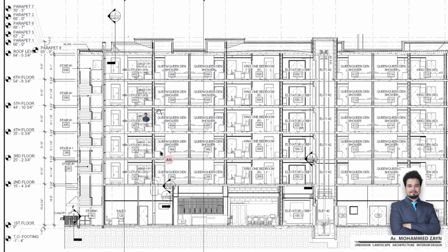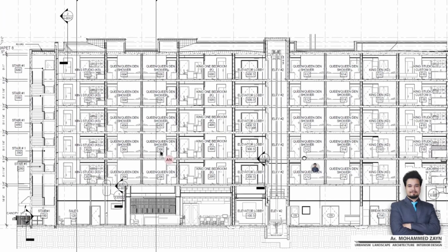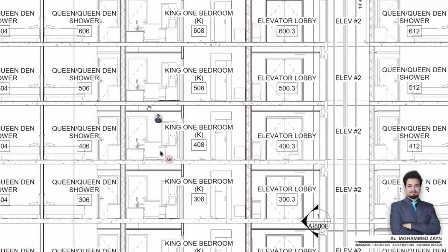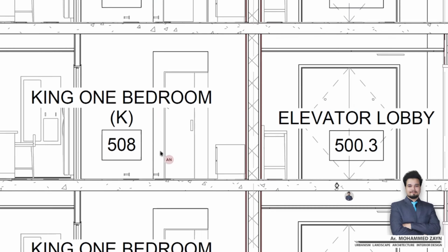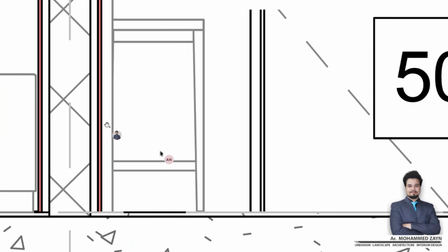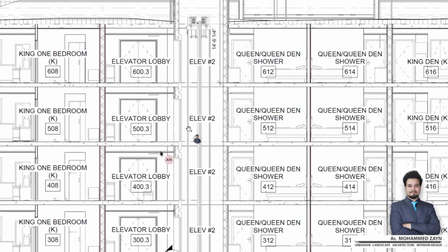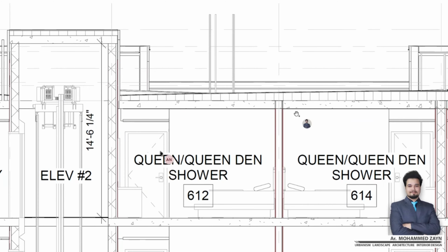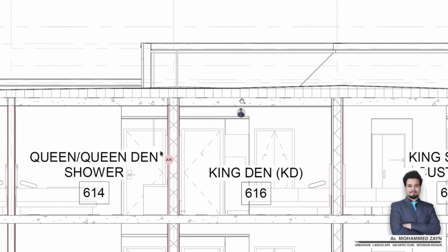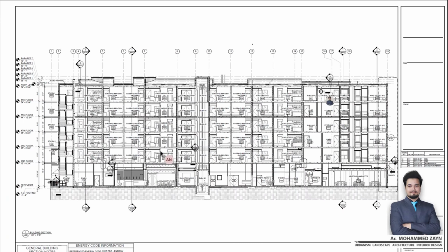These are the sections that we have created. So you can see how detailed the section is. You can even see a single family that we have placed in the previous sheets. So when we say Revit is a 3D software, this is how interrelated it is. When you place one family onto one view, it appears in all the views.